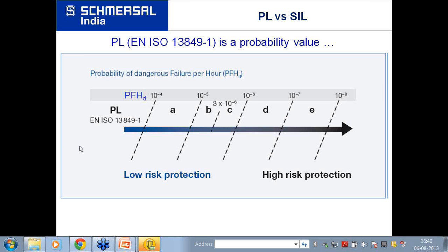You can have a dual system of reading it, but I'm not very sure about it. But from the safety point of view, if that pressure reading leads to switching some valves on or off, for example if there is an overpressure and a valve should automatically close or open, then you should have a safety valve and use the same dual channel system and the same feedback functionality. The philosophy remains absolutely the same. But if it is only for a display system, I'm not very sure about this system.